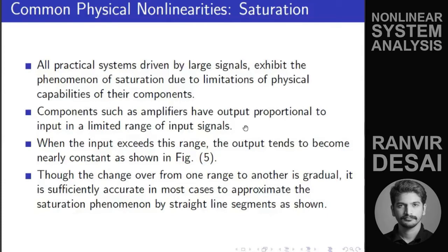Now if you give input to that amplifier, let's say 1 volt, are you able to get 1000 volts as output? In theory you should get it, but you don't. The amplifier has some limits, and that limit is basically called saturation. It may have a limit of, let's say, plus minus 10 volt, so beyond 10 volt it will fail to do the amplification. That saturation can be translated into input terms as 10 volt by 1000, which is 10 millivolt. Beyond 10 millivolt, it will amplify, but the output will stay at 10 volt.